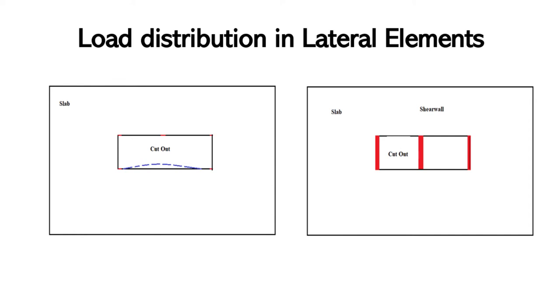So if you assign it as a rigid floor diaphragm, then any kind of internal element, like here you can see, the internal element is the concrete shear wall, won't experience any kind of in-plane action like in-plane stress. That's because you are analyzing it by assuming that the entire floor would behave as a rigid floor. So any internal deformation that would have transferred stress to that shear wall would be ignored if the rigid floor diaphragm had been assigned.